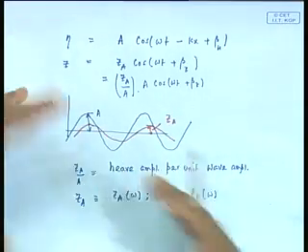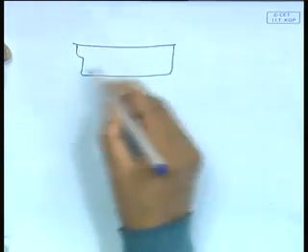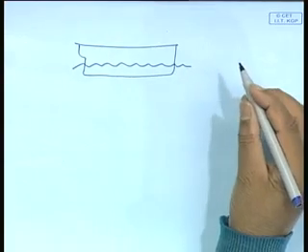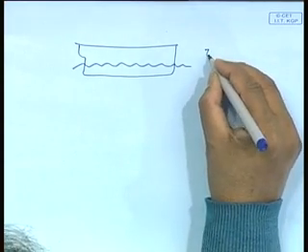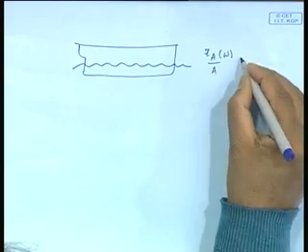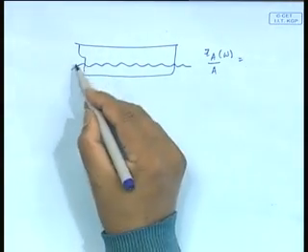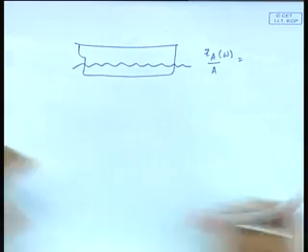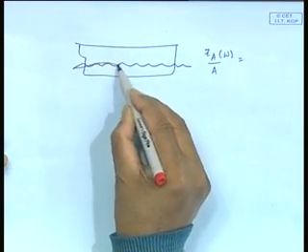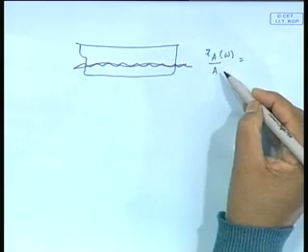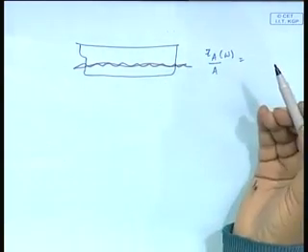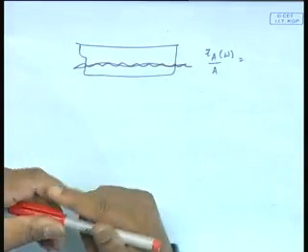Why? Because it is very common physics. If I have a 100 meter long wave, the amount it will move up and down is not going to be same as when I give a 200 meter long wave, or a 50 meter long wave. I give an example in a minute. Suppose you have this large ship. Okay. So, I have a very small wave, very small omega, let us say. So, what happened? It has a heave for this omega. This is going to be some number, but now if I put the same ship under a much longer wave of same height A, same A, do you think that this will be same? Of course, it will not be same, because it depends on the wavelength. So, therefore, ZA by A obviously is a function of omega or wavelength.